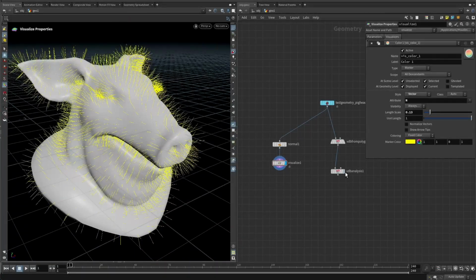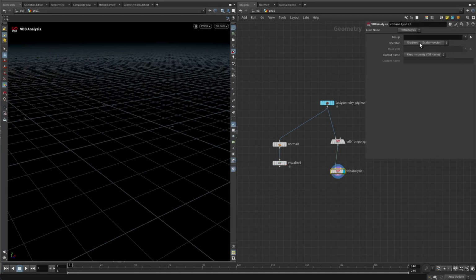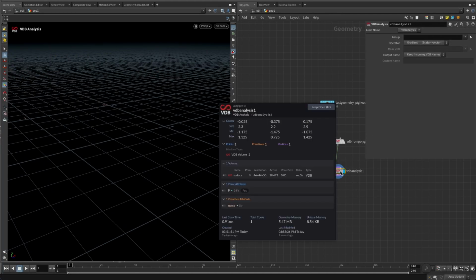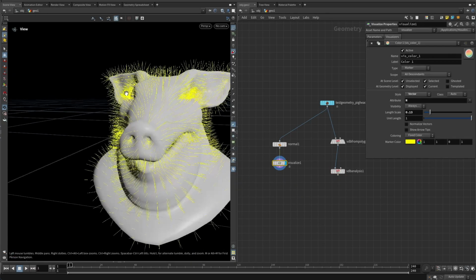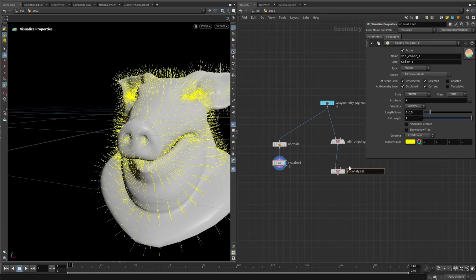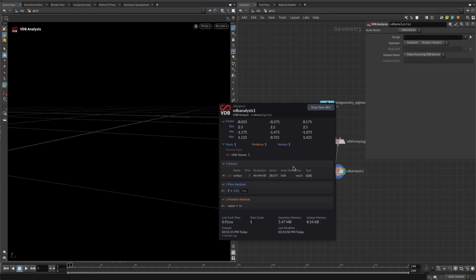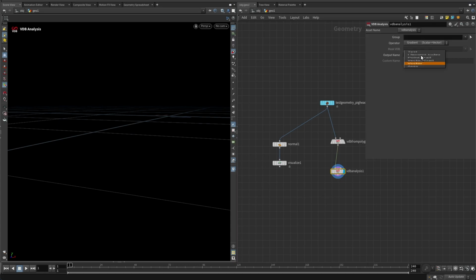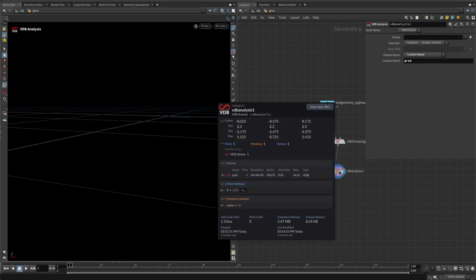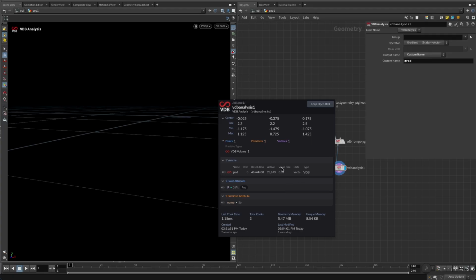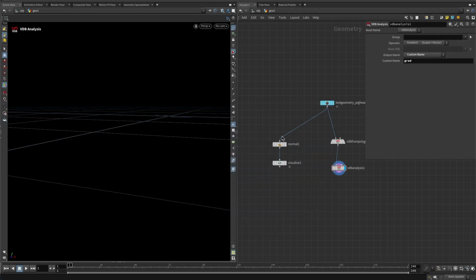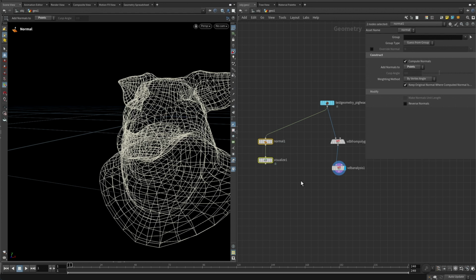This is essentially the same thing. The gradient is creating that, but as a volume field, a vector field. As we talked about, directions are vectors, and this one needs a vector to create that field. And we can change that name in here to grad, maybe. Doesn't matter, but just so you know it's possible. And I can show you that we can sample this volume and get the same result as we have on this normal, or close to that result at least.